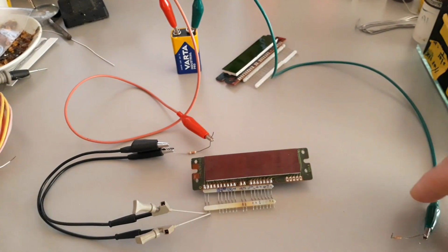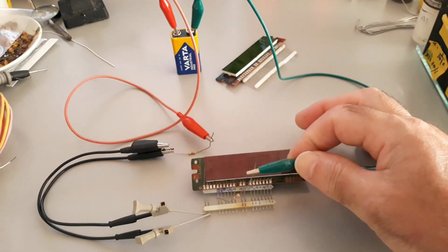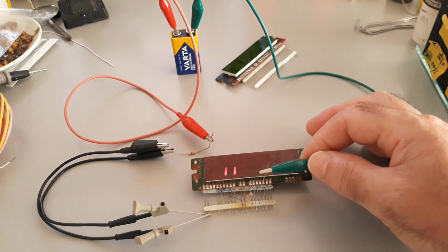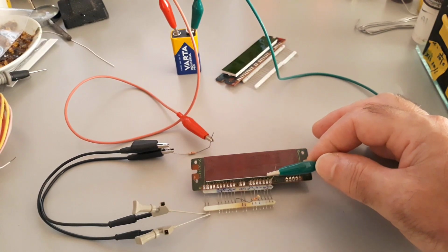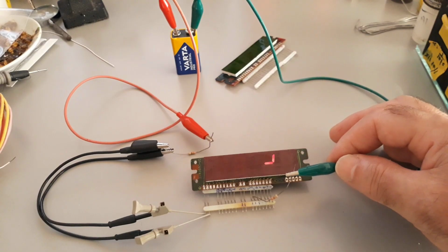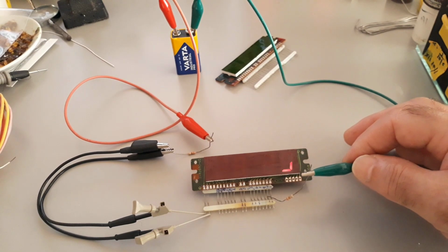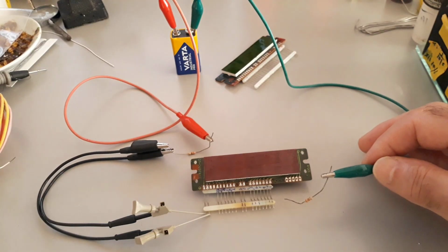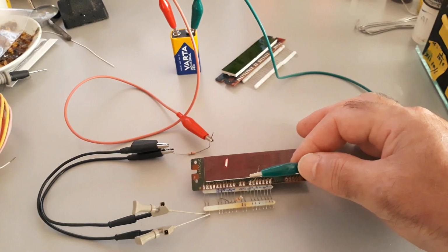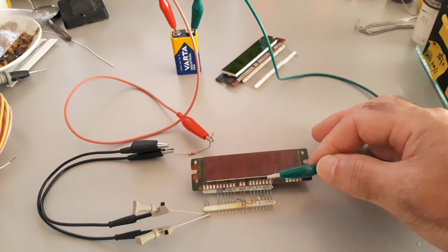The method shown here can also be used to determine whether a display is common anode or common cathode, while at the same time helping identify the segment pinout. For this test, I used two 330 ohm resistors, one connected to each polarity. After this brief introduction to the MM5457N, bringing one of these vintage clock circuits back to life becomes a very straightforward task.